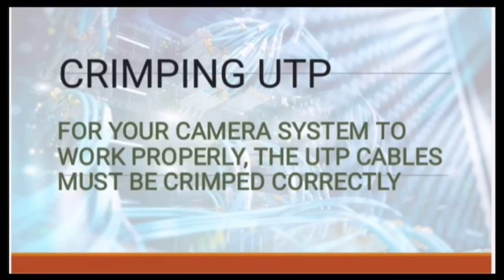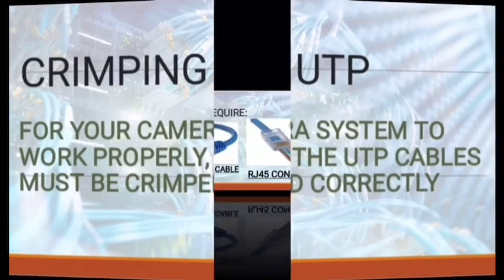And next, I will be discussing crimping UTP. So what is crimping? Crimping is joining two or more pieces of metal or other ductile material by deforming one or both of them to hold each other. The band of deformity is called the crimp. Crimping UTP is necessary for your camera system to work properly. The UTP cables must be crimped correctly.